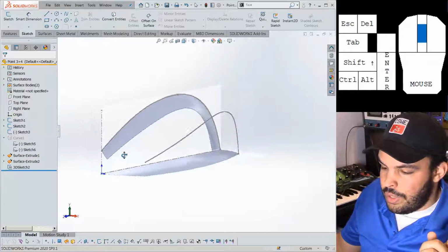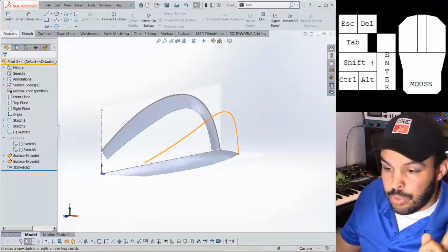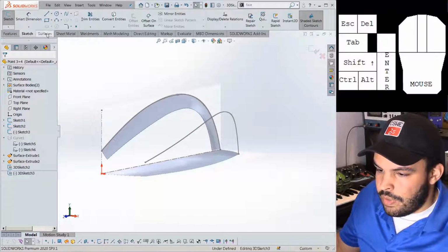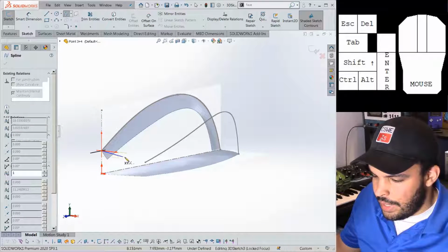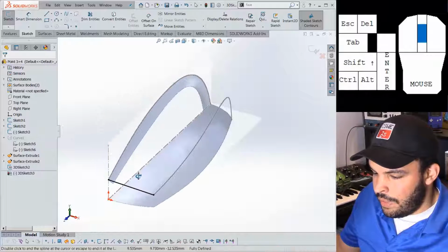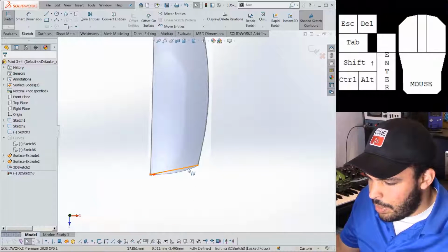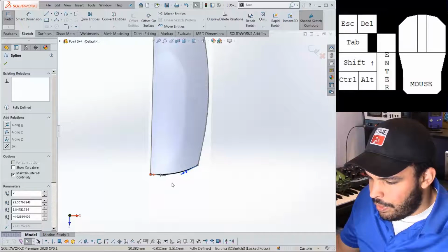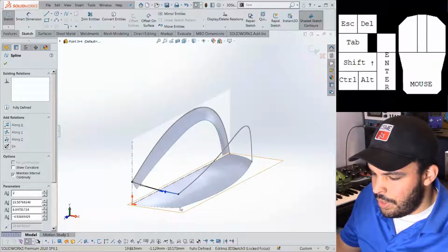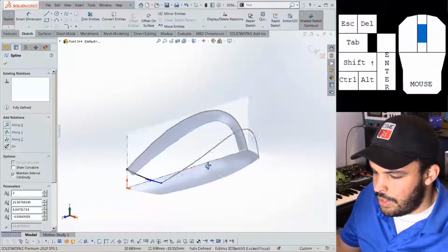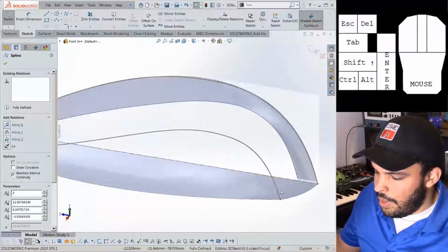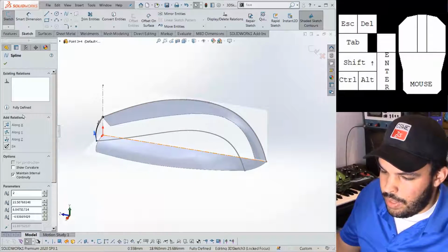A good example of how you can use perhaps a 3D spline but between 2 points. So if I get 3D sketch, a spline, and if I have 2 points, that makes this a lot more controllable. Although for this, I probably still want to just project it on by drawing this here. But yeah, you have something like that. Now I can just sketch that last thing if I want and then close it up. But the point is, get comfortable with spline sketching and try not to do overly fancy tricks. Sometimes the smaller steps building up to the bigger things is the way to go.